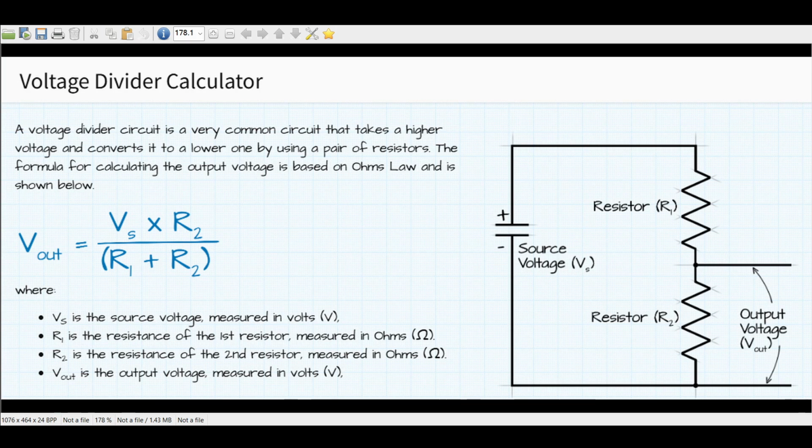All right. Now, how do we calculate? This is the circuit diagram of the one that we had created just now. This is the source voltage, positive side, negative side. This is resistance R1, which is 1K, and this is R2, which is 2K. And we want to calculate across R2. We can also calculate across R1. I have set up the multimeter across that also. So let us do the calculation across R2.